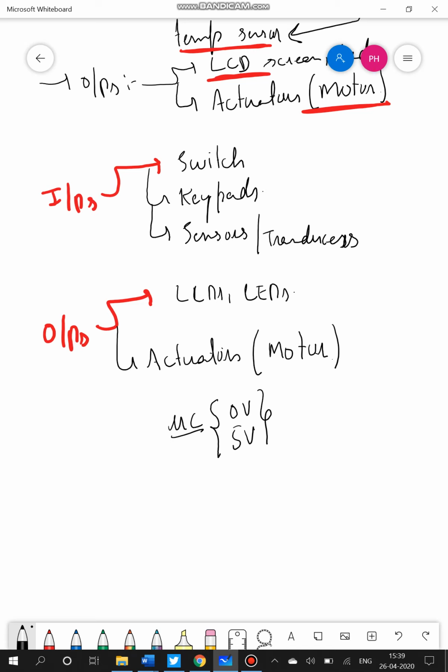So before connecting them to the microcontroller, we have to find a way to change the output of input devices to an output that is recognizable by the microcontroller. And in terms of actuators, they might need more power, more voltage, they might run on 12 volts instead of 5 volts, they might need high current that a microcontroller may not be able to give. So we have to connect to these devices using interfacing circuitry. We will be discussing all these things in this unit.